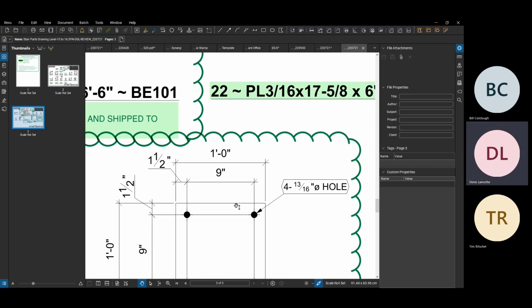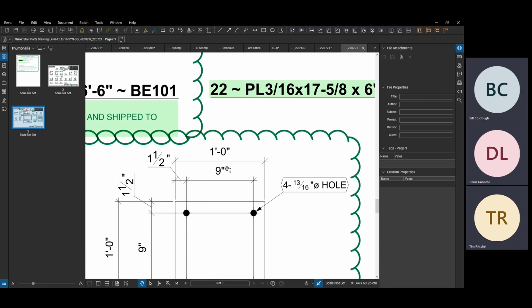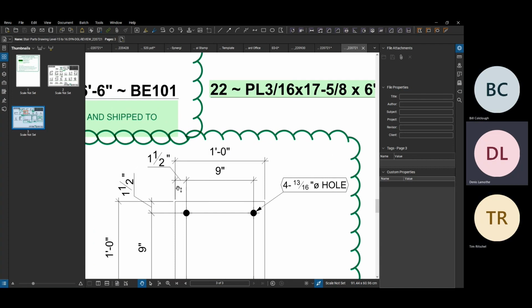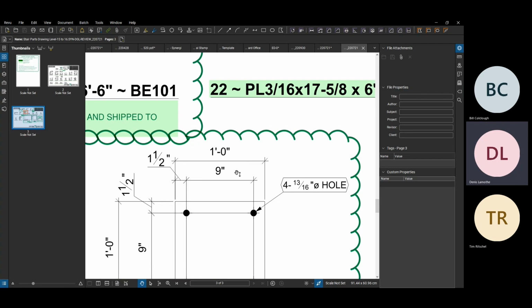We've had a couple of situations where the shop guys came to us and said, "Hey, I know you're showing this dimension, but when you add it up, you're off by 1/8 of an inch from your overall. What's going on?" And then you're stuck trying to explain, well, it's how you round numbers. If it's a 32nd of an inch, CAD will round it to the nearest 16th unless you specifically state that you want it measured at a 32nd.